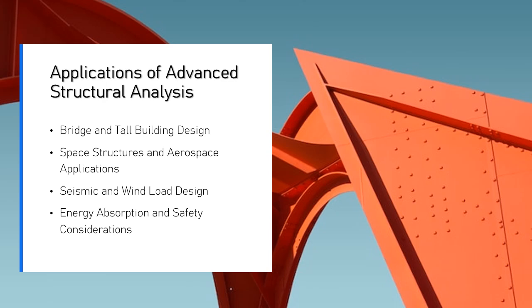Case study: Burj Khalifa, Dubai. Challenges: the Burj Khalifa is the tallest building in the world, and its design had to account for extreme wind loads, seismic forces, and the building's height-induced dynamic behavior. Advanced analysis. Tools like ETABS and SAP 2000 were used to model the building's structural response to wind-induced lateral forces, which are particularly important for skyscrapers.